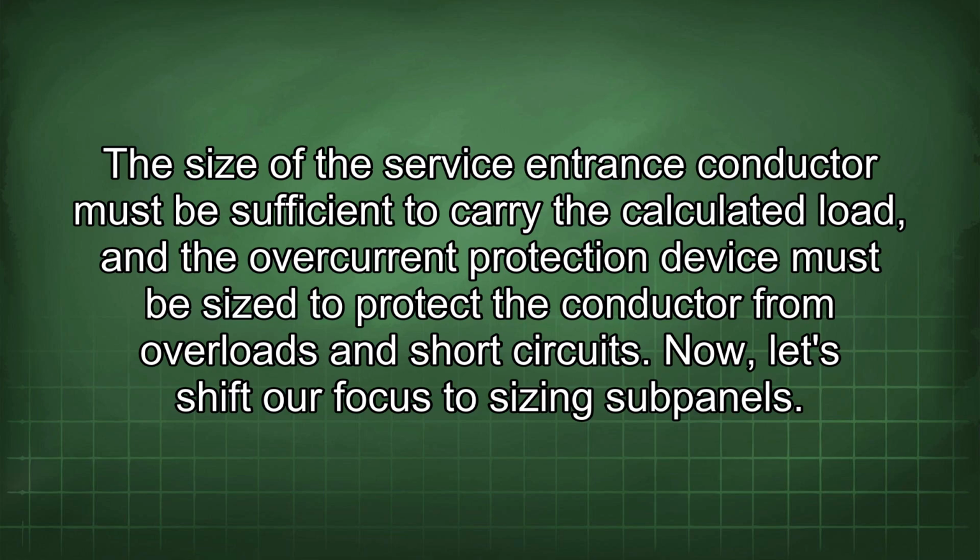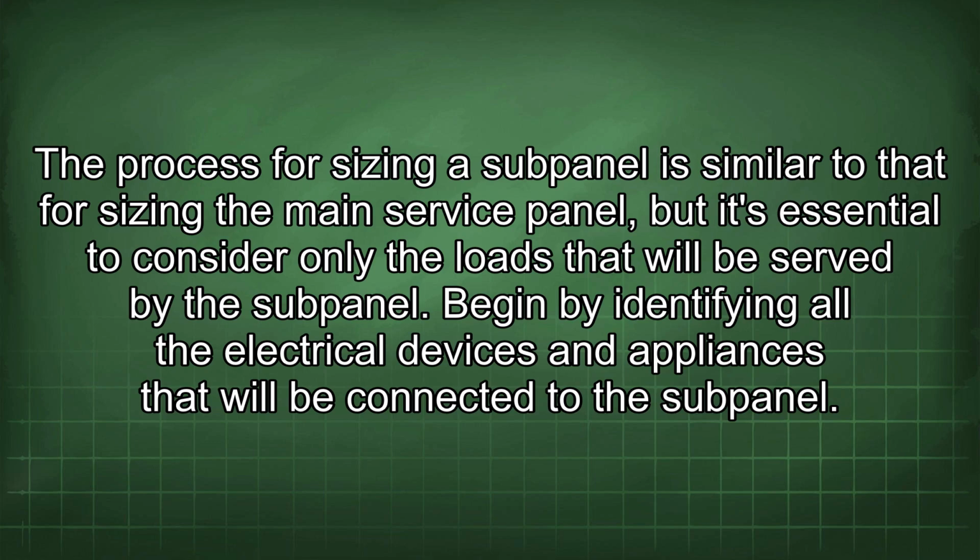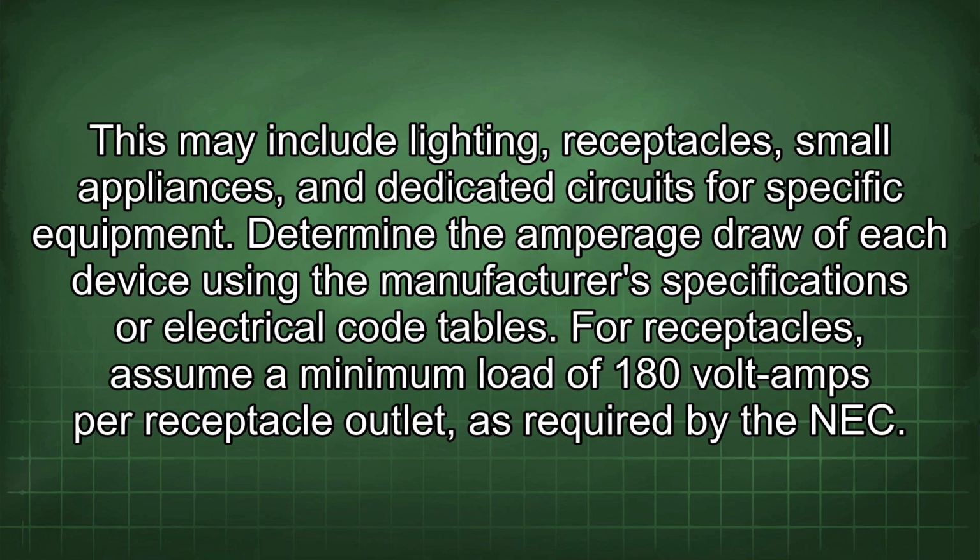Now, let's shift our focus to sizing subpanels. The process for sizing a subpanel is similar to that for sizing the main service panel, but it's essential to consider only the loads that will be served by the subpanel. Begin by identifying all the electrical devices and appliances that will be connected to the subpanel. This may include lighting, receptacles, small appliances, and dedicated circuits for specific equipment.